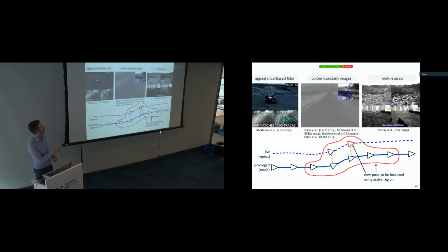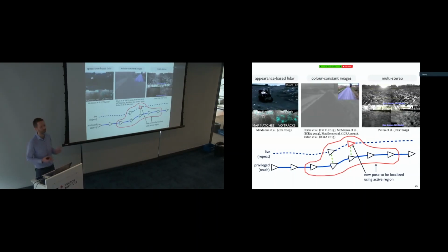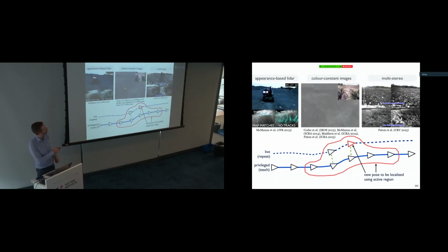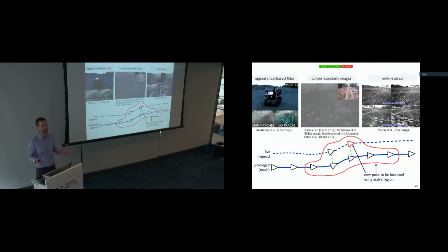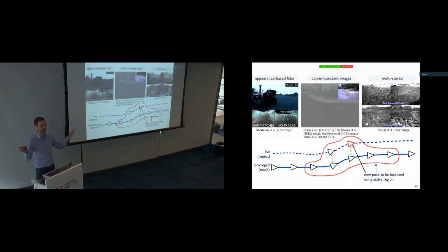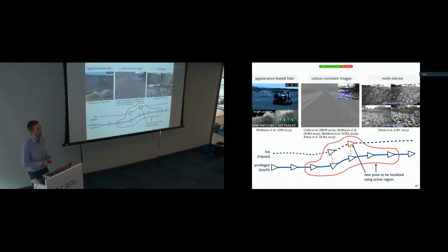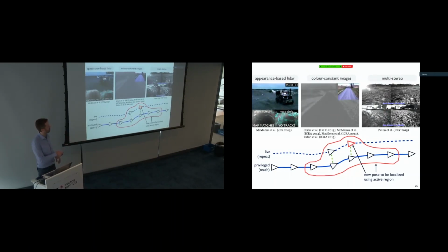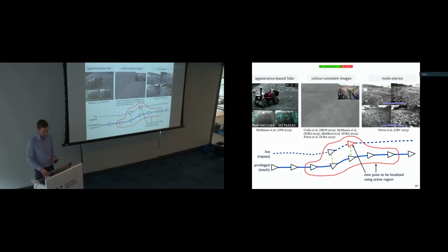You can do things like classical computer vision techniques, like color constant transforms. So you can combine the red, green, and blue channels in clever ways to sort of remove the effect of lighting and just provide the material property of what you're looking at. So you can kind of see here, that's removing the shadows in the images. Then we can operate on these images instead. We can even do really simple things like just put more cameras on the robot so that they're pointing in different directions so that when things like sun flares happen, they tend to not affect all of the cameras at the same time. So these are all really band-aids on the problem, I would say. At the end of the day, we're still trying to match this pose to here. And if this matching function fails, we're kind of cooked. So what to do?